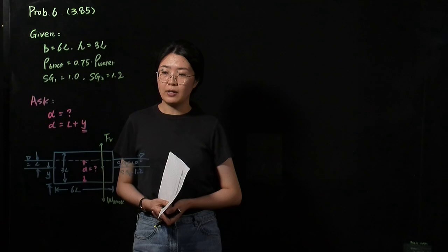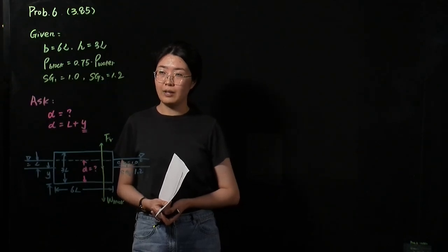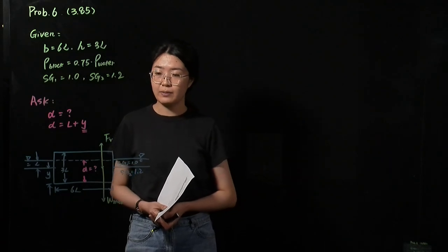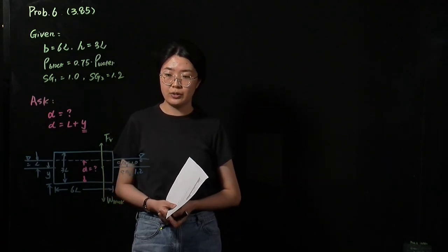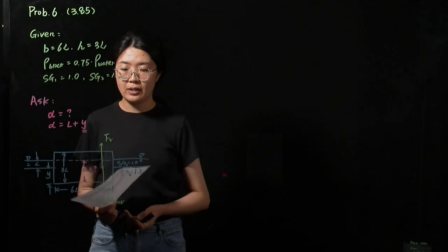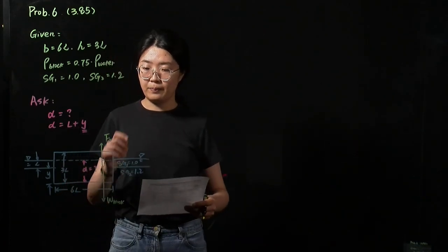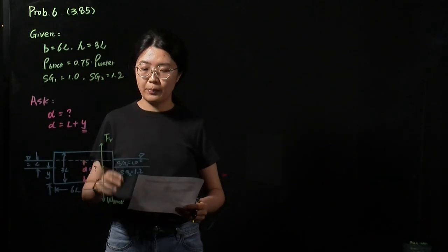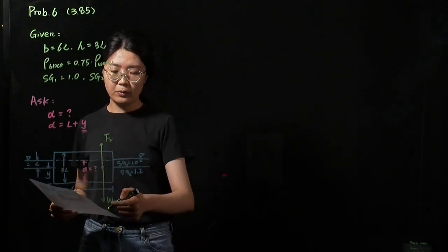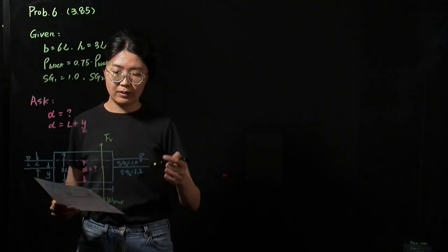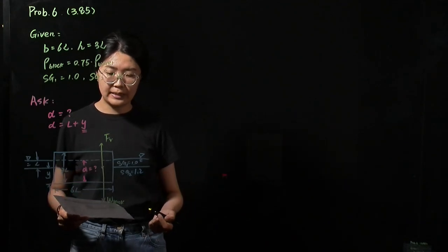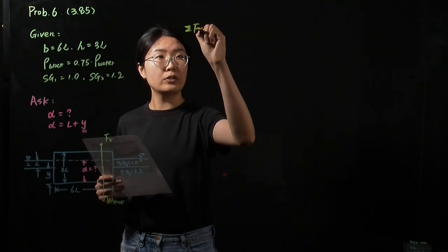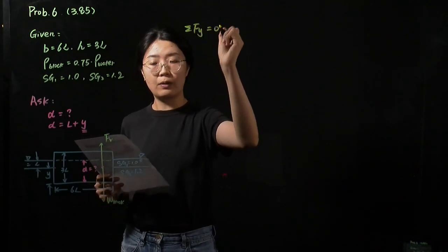Now let's solve this problem. Because this block is stable, the vertical forces exerted on this block should equal 0. There are 2 forces. The first force is the buoyant force. The direction of this force is upward, and another force is the weight of this block. The direction of this force is going down, which means the sum of the vertical forces equals 0.